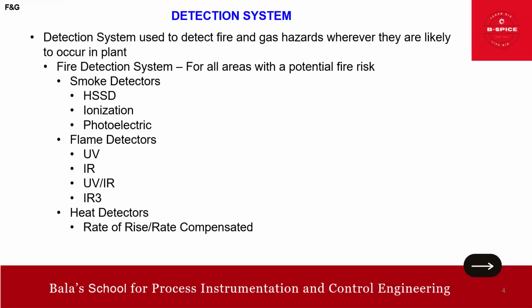That is the beauty. So let us see how it works. So basically, as I said, it's a rapid temperature detection. What is this rapid temperature detection? It triggers an alarm when the temperature rises by a certain rate. Certain rate in the sense typically 6.7 to 8.3 degrees centigrade per minute. Okay. Rapid temperature detection, that feature is there.